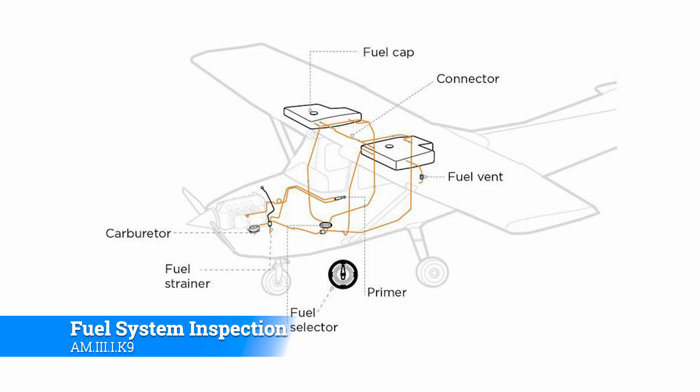The next thing we're looking at in the entire system is making sure that there's no water in the lines whatsoever. Also sediment. You'll have seals that will start to break down. You'll have dirt and grime and all kinds of things that can happen inside the fuel lines. You want to make sure that gets removed, and then the source of it gets plugged or taken care of, however you possibly can.